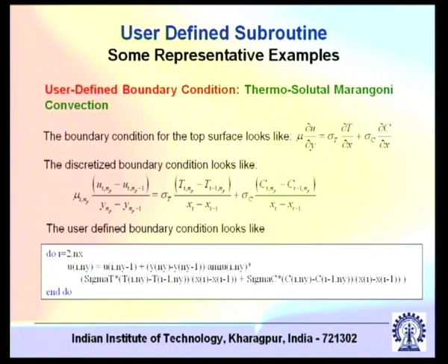Now you may have a temperature gradient on the surface of the liquid, and for most liquids, the surface tension is a strong function of temperature. So if you have a gradient of temperature, it induces a gradient in surface tension, and because of the gradient of surface tension it can induce an interfacial flow which we call Marangoni flow.